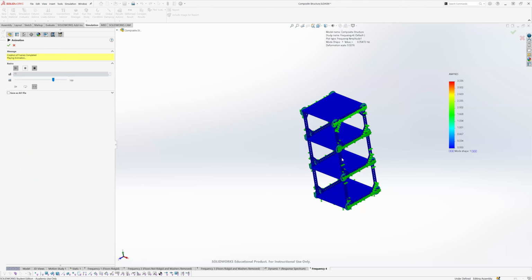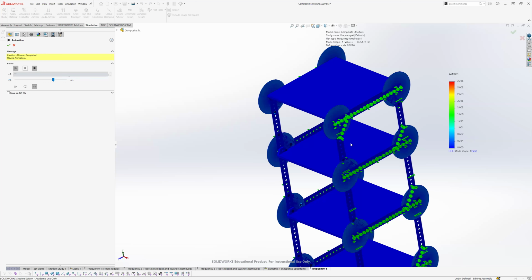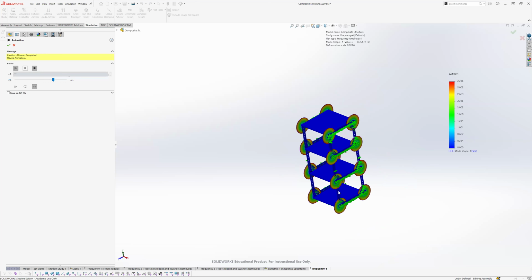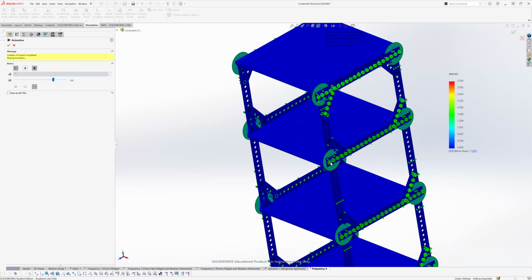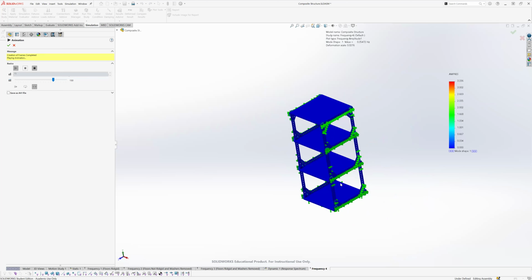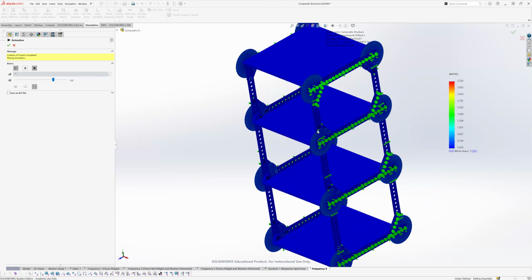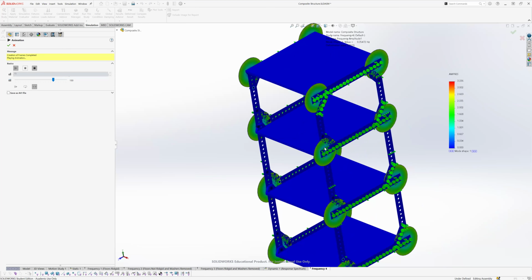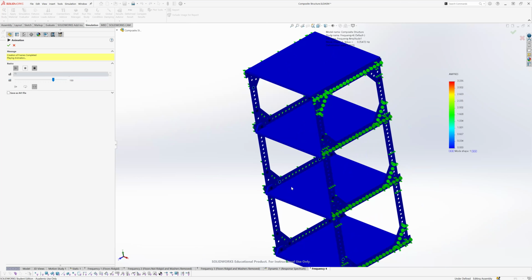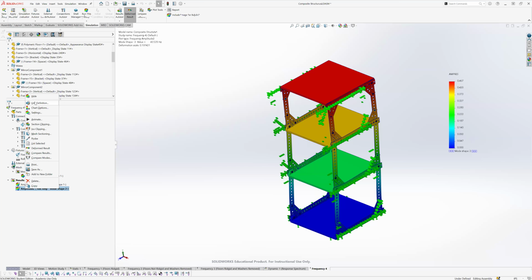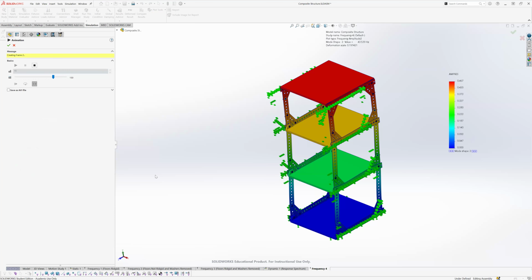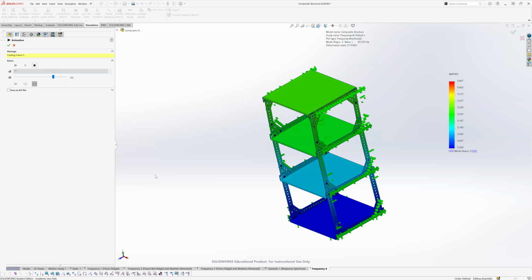So obviously, just by looking at this, in real life you can look at this and say this is not something that would really happen. So theoretically, if it vibrates, it could technically expand on a micro level. These washers could. Obviously, this is just an exaggerated deformation scale. But that's not a big concern for us, especially since there's such low mass participation in this. So we'll ignore that one for now, and we'll go over to amplitude 2. So this is going to be obviously our dominant mode here. So let's animate this as well and see what we're looking at. So again, we'll let it go.